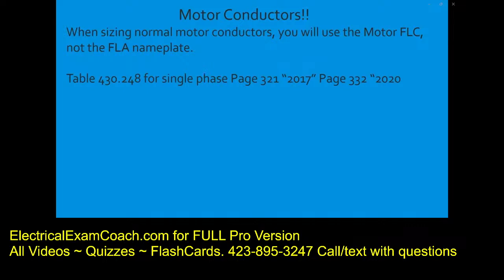Okay? And one thing I want to note is that these are nominal voltages. So, although it says 115 at the top, it would also include 120. Although all the way at the end, it says 230 volts across the top of the black bold headings, you could still count 240 in that. These are nominal voltages. Another tip I want to give you is that even if the motor is a single phase motor, but your question states 208 volts, you use whatever column your question states. Don't try to use reasoning and say, well, 208 is only three-phase. Whatever your question states, just do it that way.